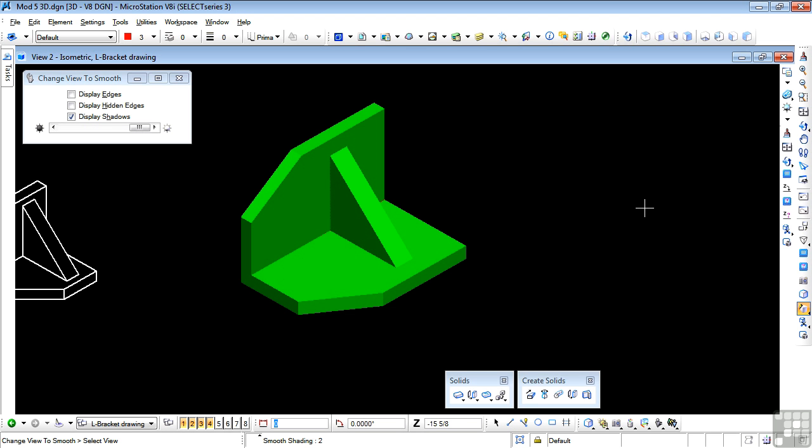For example, having an object with many assembled but separate parts can be a problem when editing the object, since each part must usually be edited separately. This problem is addressed in the next set of videos, where you learn to use Boolean tools to convert the parts into a single whole, and where you will draw the web-shaped angled object again using another tool. So please practice that. It's a neat little exercise to develop skills with the Solid by Thicken Surface tool.